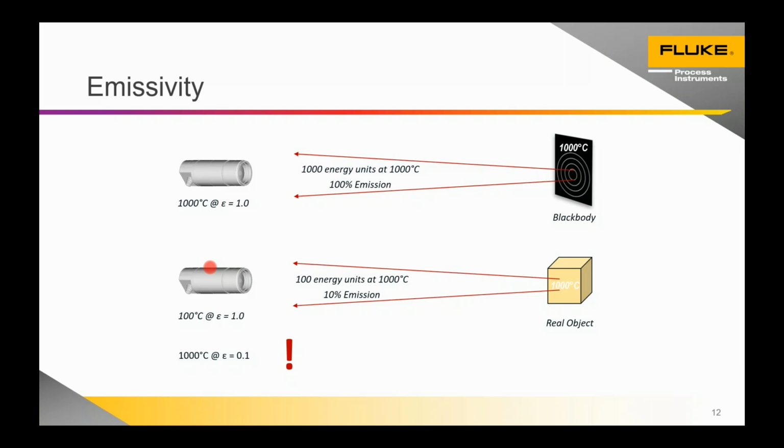Yeah, I would add that a lot of people who own these pyrometers, even a very high-end one, don't calibrate on a regular basis, and I think the reason is that a user's ability to know the emissivity of the target and the effects of things like background temperature and perhaps the transmissivity of windows that you're looking through, generally those things specific to the application can add more uncertainty into your measurement than does the drift of the instrument, which is usually smaller. Electrically, they're very stable. Yes, that's right.